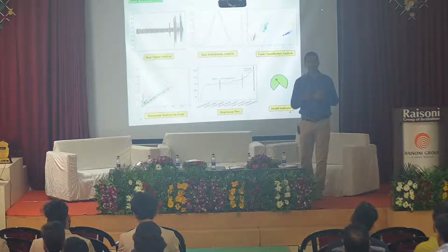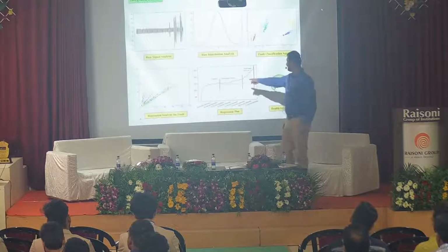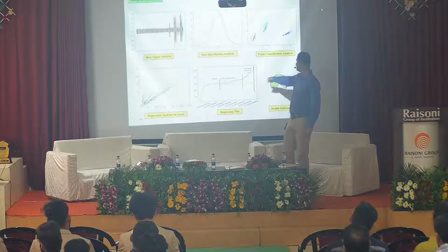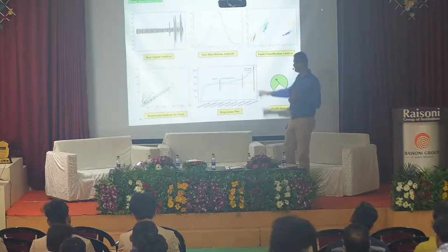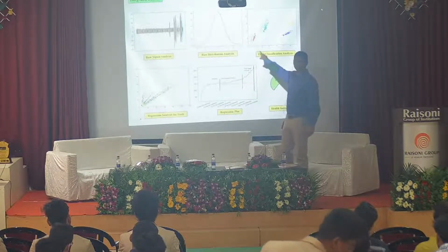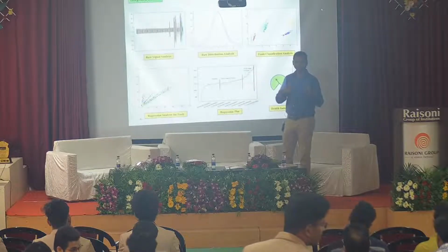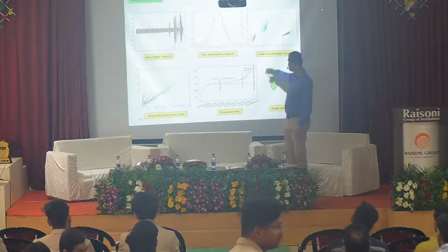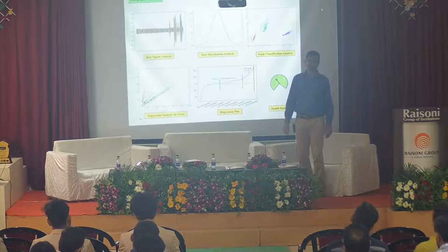take preemptive measures. If you observe this, over there the vertical green line is where the fault has occurred and the machine can run up to this point. So I have that much time to adopt a maintenance policy and take a decision. You see that was the normal curve, then it started to increase exponentially. So once the fault occurs and you still use that machine, it's going to fall down very quickly. So that is the trend. I need to have that analysis, and then I'll get health indicators basically.